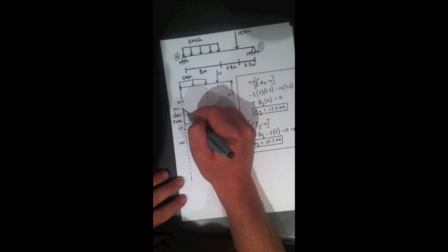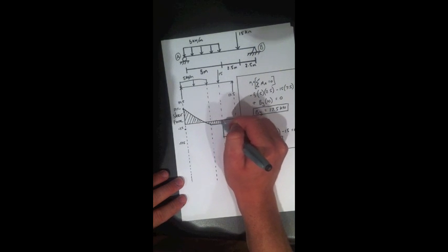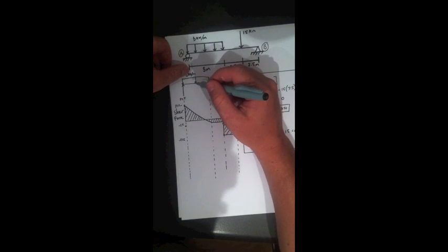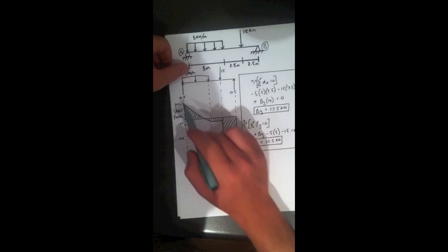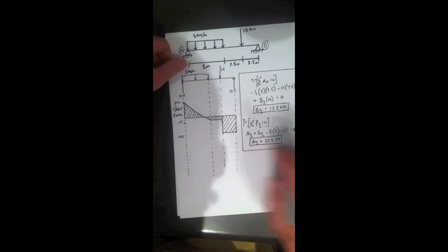It's important, if that doesn't go back to zero, then it's not really a static problem, so you've probably done something wrong. And then I just like to make my life easier by drawing them in. And that there is your shear force diagram. The only trick there is with the 5, you've just got to think it's going to be an angle sloping down, and it's going to make a triangle shape. That's probably the most basic distributed load, but that's all we're going to focus on at the moment.